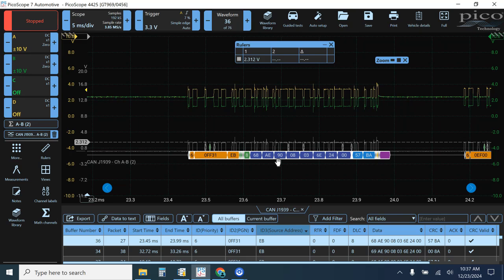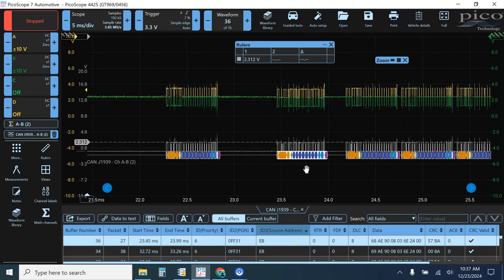You might have also noticed that this device, EB, even though it doesn't transmit very often, was really disrupting the CAN bus. The likely cause is that even though it only transmits maybe once or a couple of times per second, it was transmitting repeatedly because there were apparently no devices acknowledging its message. So it kept repeating this message, even though it was stepping on other traffic, if you would. The CAN transceivers and the rest of the bus were able to successfully decode the same way that we were with the oscilloscope, even though the problem was there.